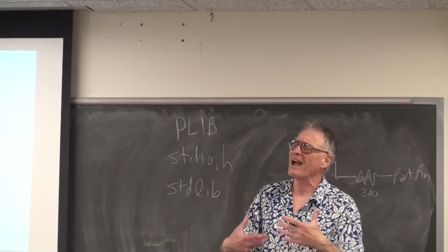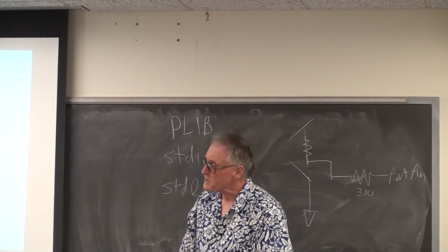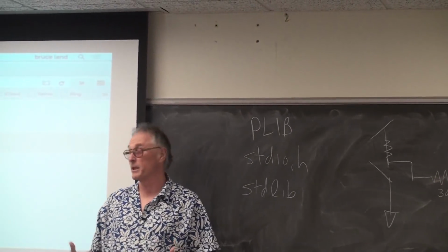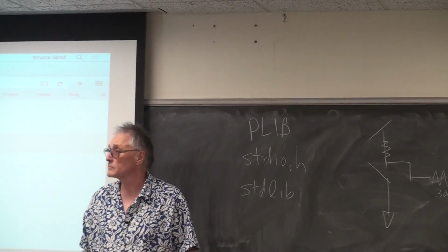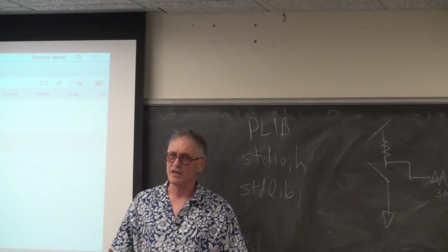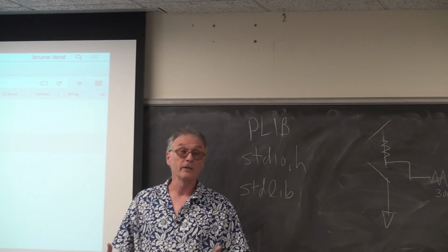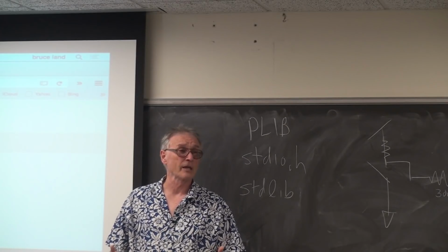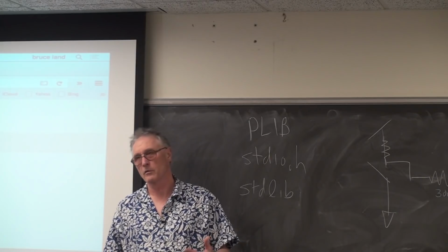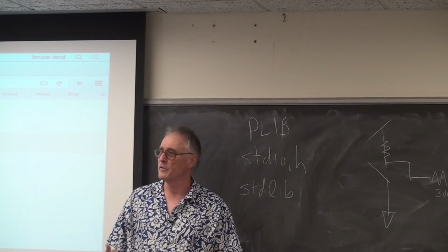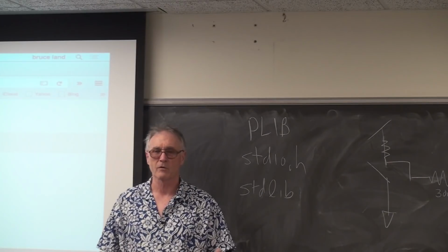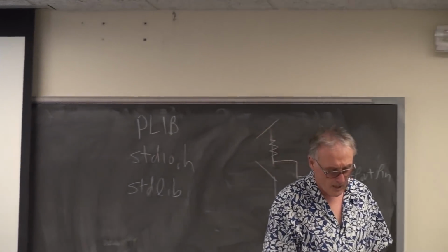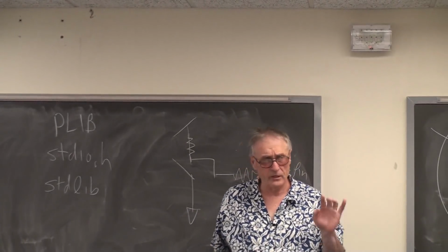So we have to talk about how you configure the phase lock loops to give you the frequency you want, which is usually the highest possible because you want performance. But occasionally, you might want to save power. And then you could drop to a lower frequency if most of your application depends upon the oh-so-slow human. There's no reason to run the clock at 50 megahertz. You might as well run it at 2 kilohertz. So there are ways of slowing the clock way down, and we need to talk about that.